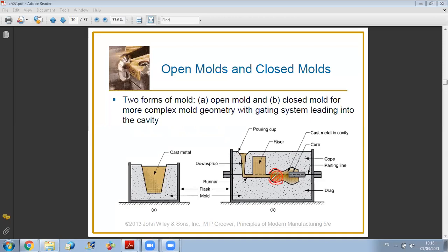Sometimes, if I don't have a uniform geometry... for example, if you consider a cylinder, this is a simple geometry. A cylinder will have one volume to surface ratio. In general, for a cylinder, it's a uniform geometrical shape. I calculate V over A. I consider the total volume, and I divide by the lateral surface, okay? Because you have contact here, and you have contact here. So you should add all lateral surfaces, and you then calculate V over A.